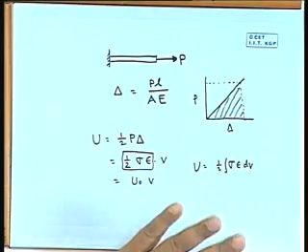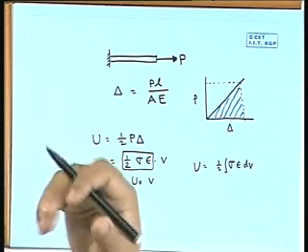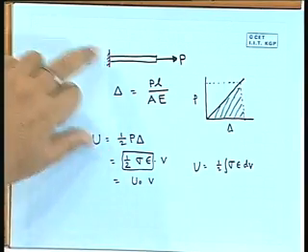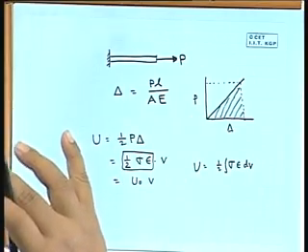Now, it is basically strain energy, related to strain or stress, so it is basically an internal thing. Though we have tried to explain it at the beginning in terms of external work, equating external work and internal work in the form of strain energy for applying a load in a gradual manner in a static condition, this strain energy concept is valid for dynamic problems also. If we apply a load, your internal stress and strain will gradually increase from 0 to a certain value. So it will not be suddenly generated. So this half term will be coming there.